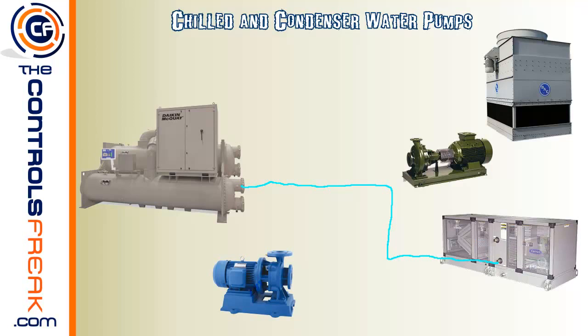Alright, so we've got the chilled water coming in at the bottom of the coil. Now we want to draw the water coming back out of the coil that's ready to go back to the central plant and get cooled down again. That'll be this darker color here, and we'll send it this direction. And I'm sorry, pipes don't normally go on a diagonal slant like that, I promise. But it comes into the inlet of the pump.